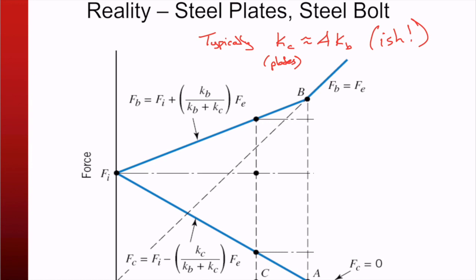As I apply this external load this way, the force in the bolt will increase some, but not too much, because this is the bolt's fraction of total stiffness, which is relatively small.